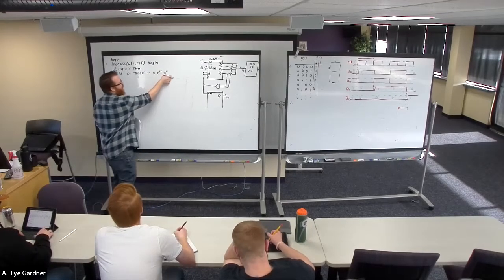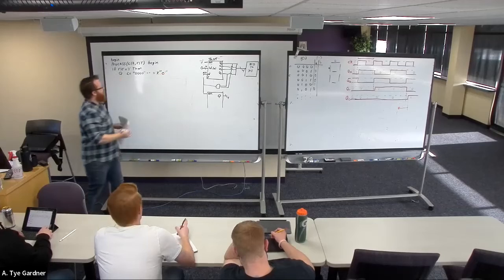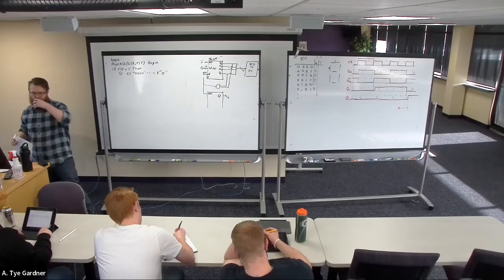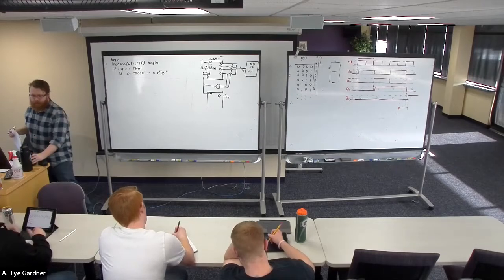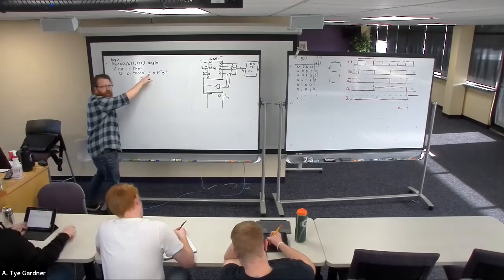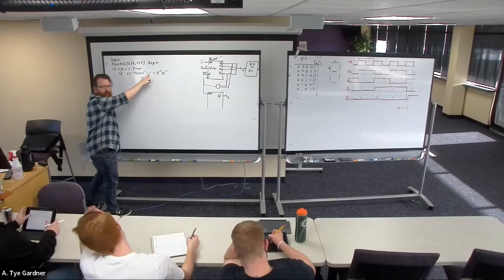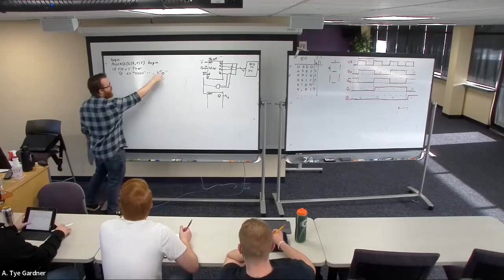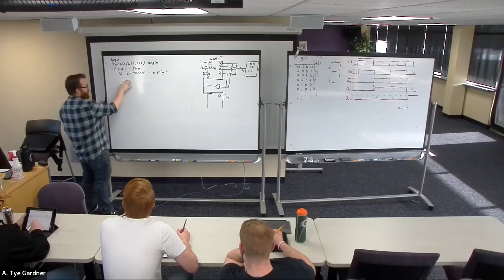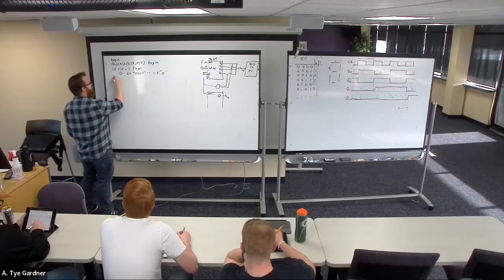So this is a hex character 0, which is the same as that. Either one of those is a fine way to do it, right? The double dash is the comment in VHDL. We remember this, meaning this code doesn't do anything. It's just a reminder. And now I've built my reset.